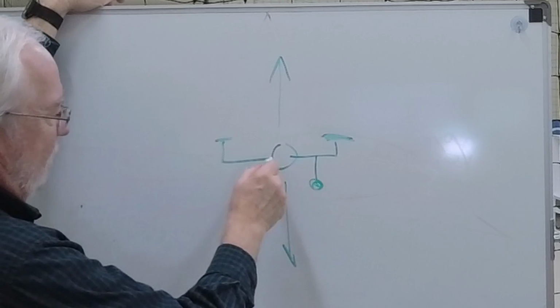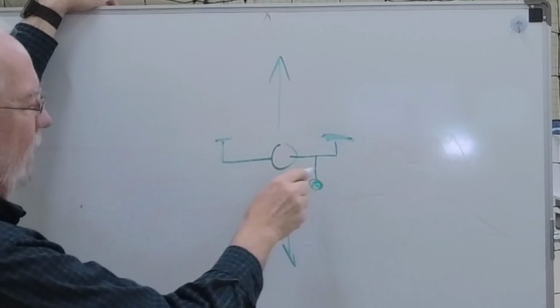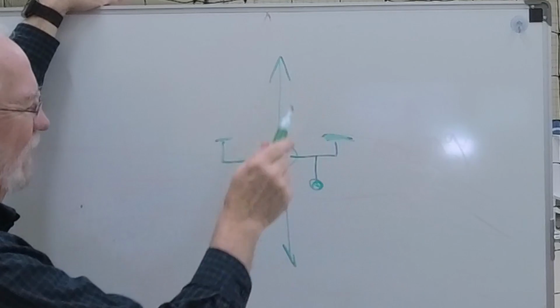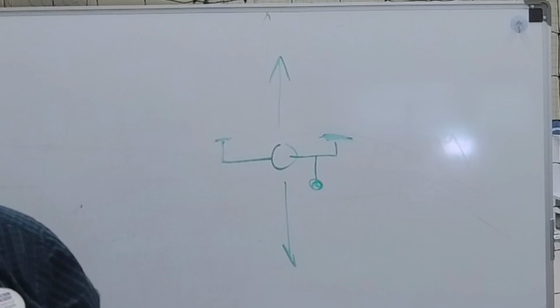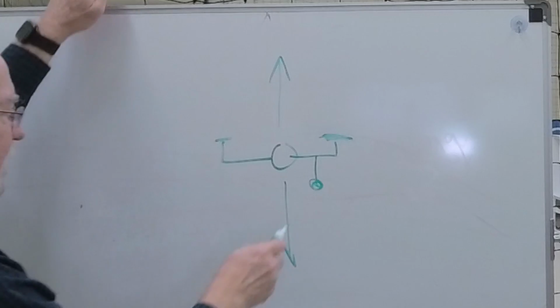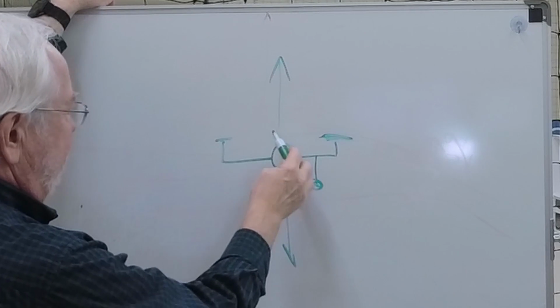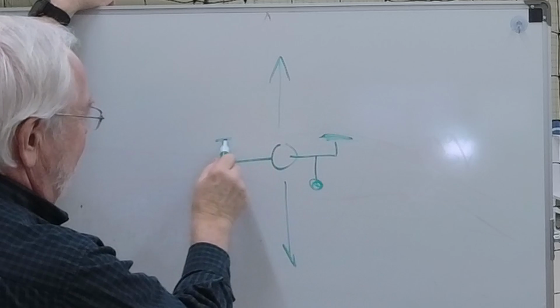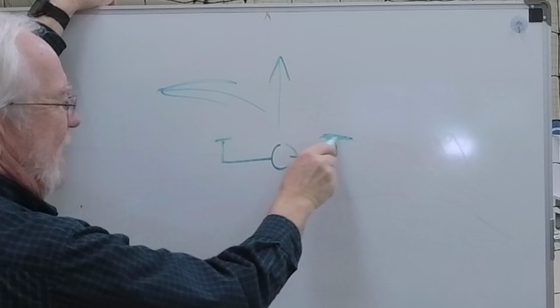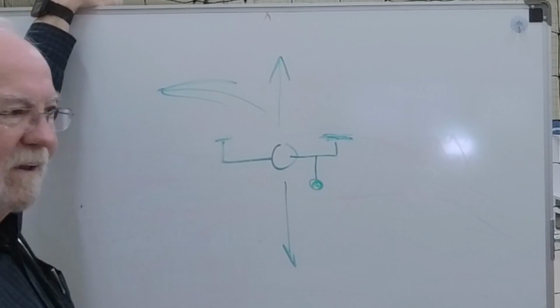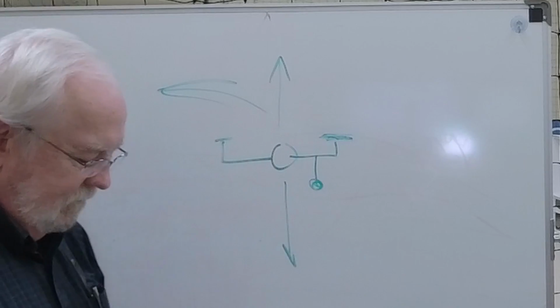It's going to create a greater need for power, whether it's electricity or nuclear powered or gasoline powered or helium, whatever. It's going to create a need for more electricity, so it's going to reduce performance, but it's also going to reduce the ability for the drone to turn that way, or no, to go this way, because it's not going to have enough lift. Well, no, go this way. When you want to turn that way, it's going to be hard because this is already running at maximum RPM just to hold the thing up, level flight, so it's not going to be as stable if you don't have the center of gravity in the proper place.